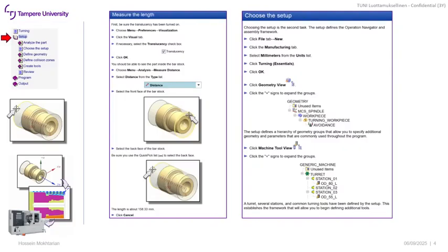In the first part, the setup, we normally need to first analyze the part that we are going to work with. This entails, for example, measuring the size of the part in case we don't have it already, the diameter and length of the part, and also deciding about the raw stock material in case we need to create it, or from the workshop floor if there are any diameters we need to have. Sometimes these are not always cylindrical parts, as they are somehow halfway machined during some process, for example. So we need to measure those parts and be ready to define them in the machine itself.